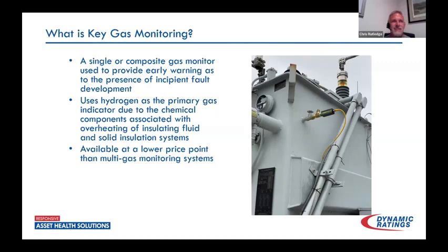And that would be somewhere around 150 degrees C internal temperature. In that transformer, we're going to start seeing this hydrogen and methane production. And hydrogen tends to generate through all of those values, all the temperatures above that. So there's been some studies, IEEE recently, where that hydrogen generation tends to go up or down, but it's always present through all these values.